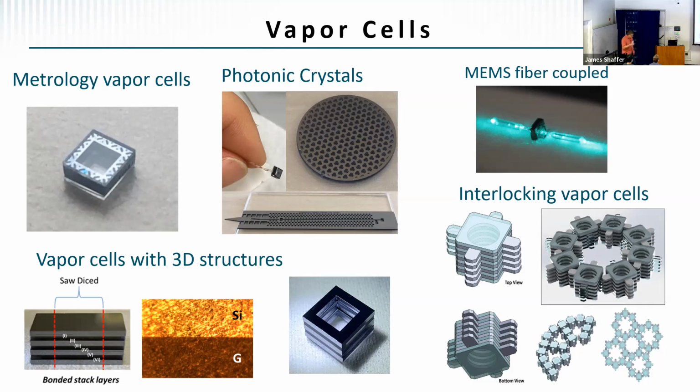This is actually built to do two different things, which is to couple in the RF into a slot waveguide here, which, because the index of refraction of this silicon slab is much different than air, we can actually concentrate the field into that gap, increasing the field where the atoms are. But there's also a photonic crystal engineered around here to slow the RF as it propagates along this waveguide, which also increases the interaction.